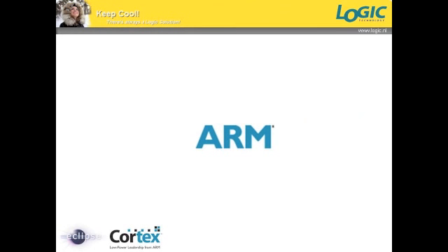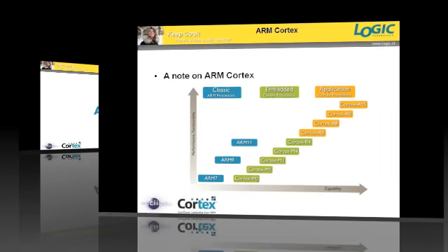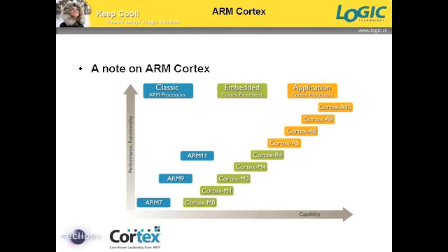The ARM architecture is the most widely used 32-bit RISC architecture. As of 2007, 98% of the more than 1 billion mobile phones that are sold each year use at least one ARM processor. Prominent examples of the ARM processor families include ARM7, ARM9, ARM11 and Cortex. This presentation focuses on Cortex. Cortex-A are application processors needed by smartphones, previously using ARM9 or 11. Cortex-R, not listed on the slide, is for real-time applications, whereas Cortex-M are microcontrollers.